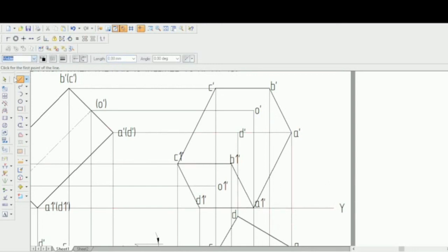So we can just see now B1 dash to B dash. If there is any line that comes within this square part, when I'm joining a line within the square part, if a line comes from here, let that line be made hidden. If a line joins from outside of this, let's make that as visible. Now joining B1 dash to B dash will be joined from the outside of this frame, so that one will actually be made visible. So that is not hidden, that is actually visible. So make that as visible.